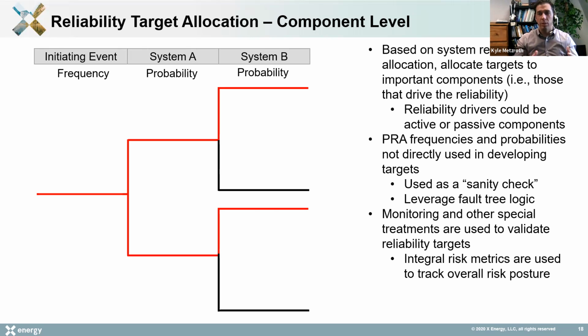And then based on this, we figure out what kinds of programmatic elements we need in service testing, in-service inspections, maintenance, et cetera, that can give us confidence that we're actually meeting that reliability target. And I mentioned a lot of these conversations came up around reliability integrity management for passive components, right? That's a key lead into it. You need reliability targets for RIM, and that helps to set what kind of inspection techniques you need to do and actually be able to verify that requirement.